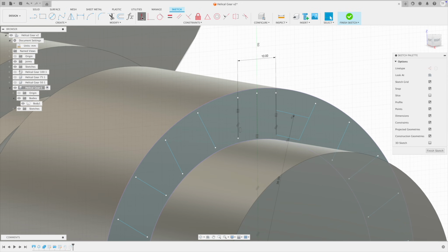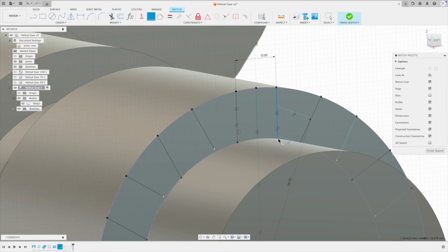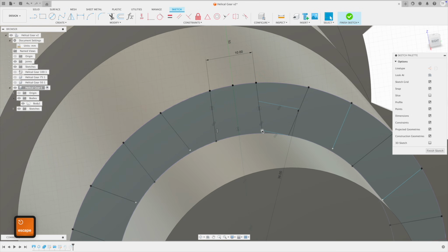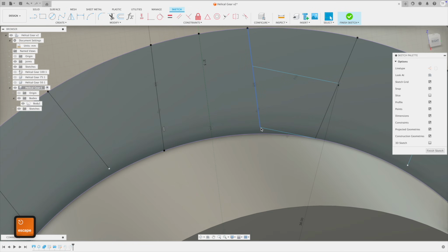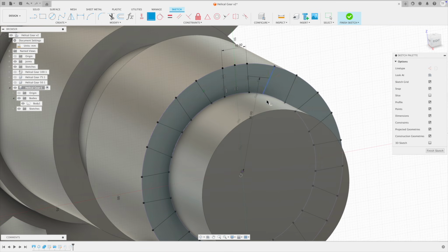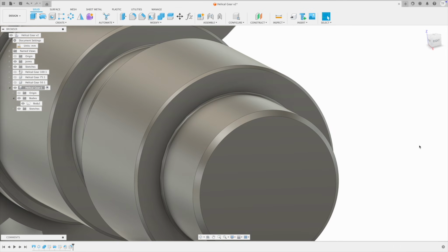Let's go to coincident, and I can just connect those lines. I can connect that to that, and then this should solve it. This is a whole lot better looking right there. I've got to go coincident, pick that endpoint. It's forcing me to pick the line. I want the endpoint coincident to that. There we go. Now everything is constrained. Everything's looking good.